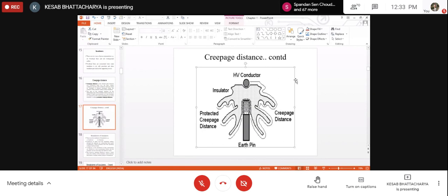If we just place the conductor without binding them on the side grooves, then during strong wind, the live conductors will be displaced. So they are always placed with binding wires, and normally the side grooves are used for holding the binding wires and the high voltage conductor. Now, here actually this is the body of the insulator.